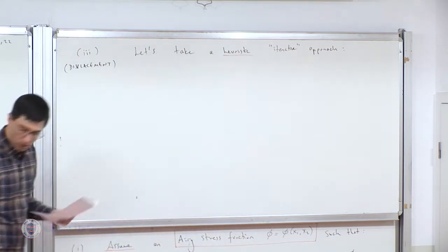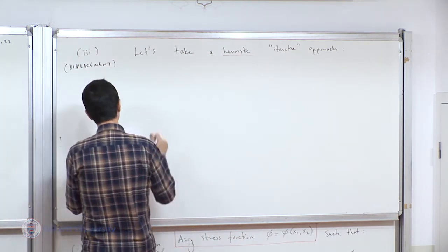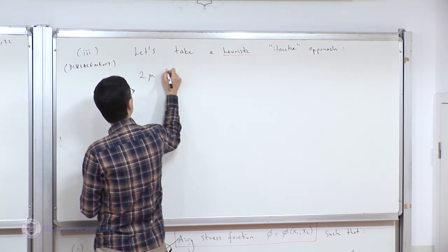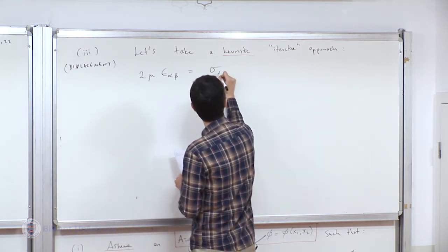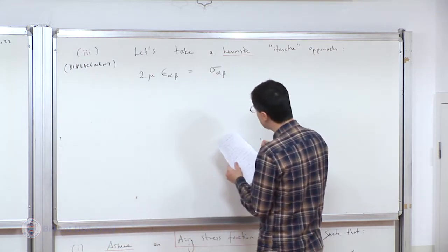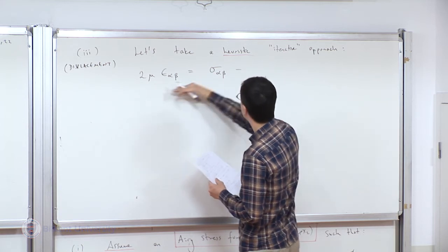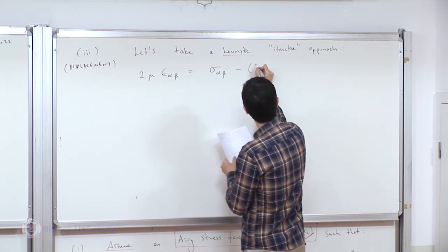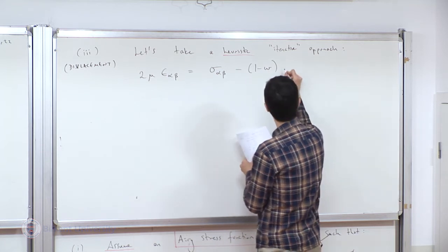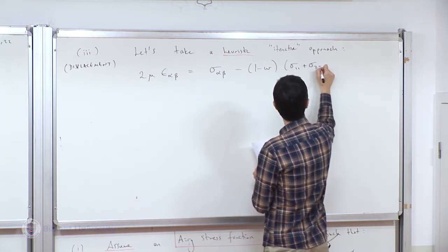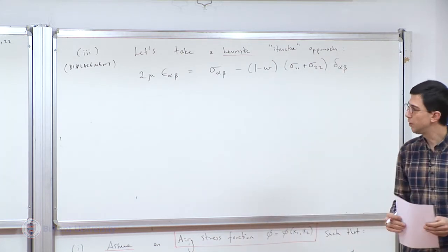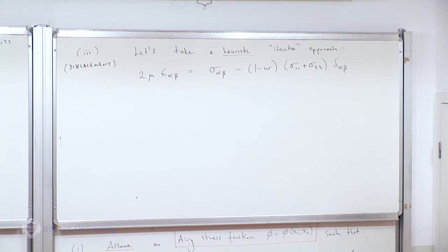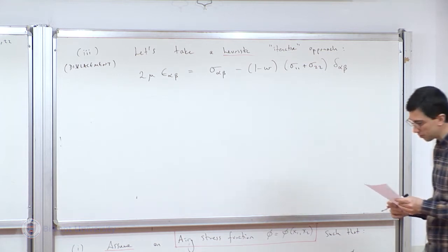Okay. So now, my starting point will be to recall the relation between stress and strain in our 2D world. Because we're in a stress-based setting, it's natural to write the strain in terms of the stress. And last time we had derived this equality. Given the stress components, the in-plane stress components, I can evaluate the in-plane strain components. So that's something we keep in mind.